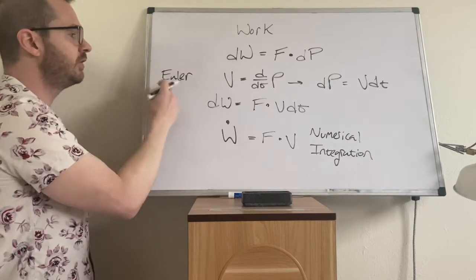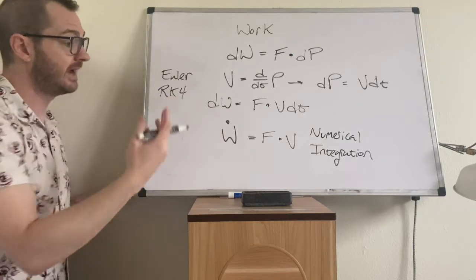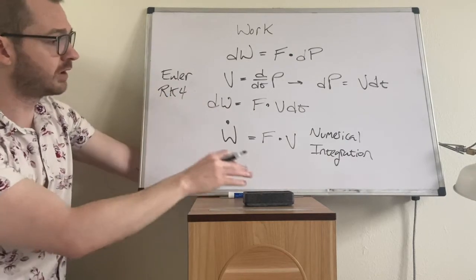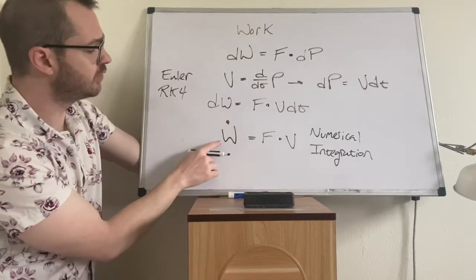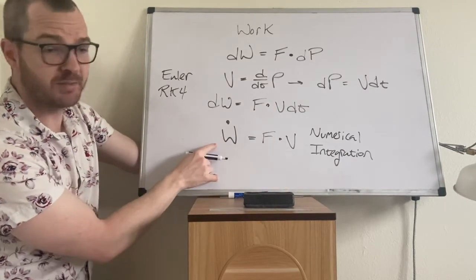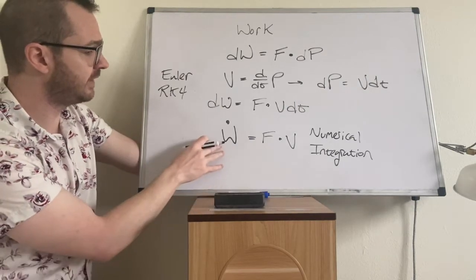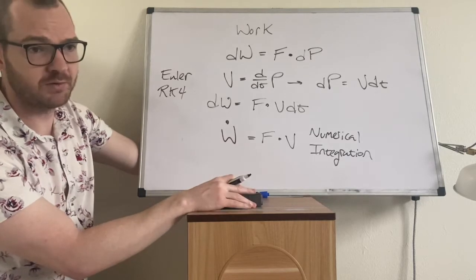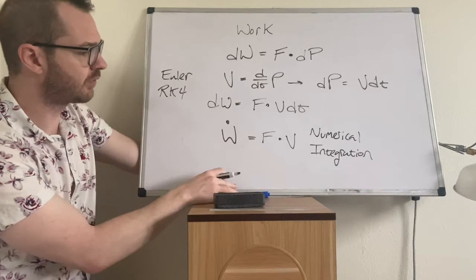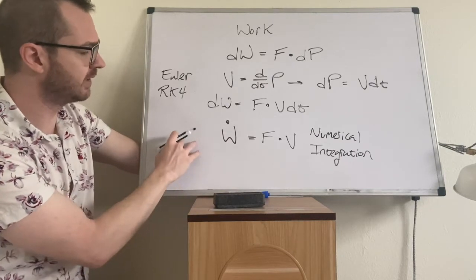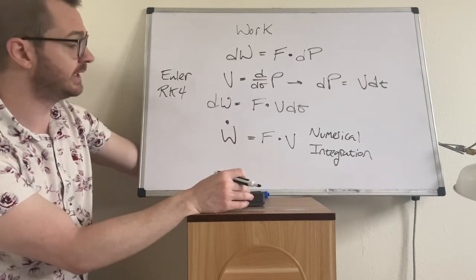in the early days, Euler's method. These days, we have much more elegant solvers such as Runge-Kutta 4 methods. But in a numerical integration scheme, you can numerically integrate the W dot as one of your state vectors. If you're interested in seeing this in practice, there are some other videos that I have posted on numerically integrating equations of motion for ballistics, and also in another channel on just the topic of numerical integration in general.